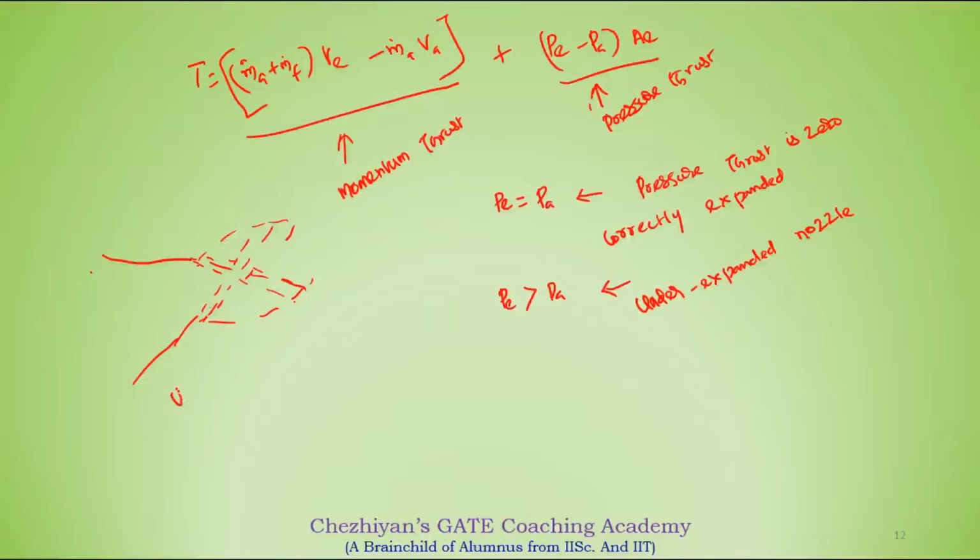Basically we call it unlike reflection in the case of a free boundary. In the case of a solid boundary, you are going to have a like reflection. In the isolator of a scramjet engine, an oblique shock is reflected as an oblique shock only. Here, like reflection.